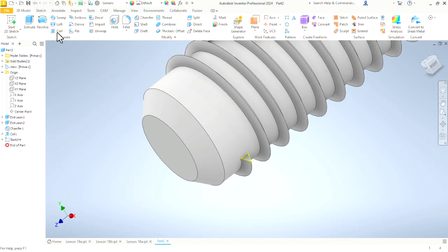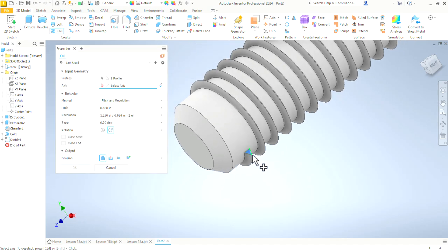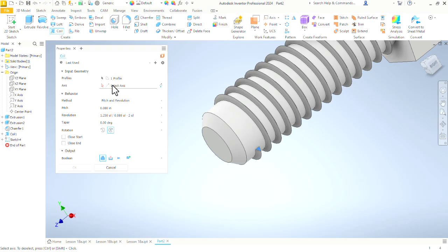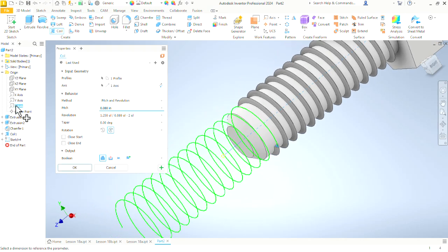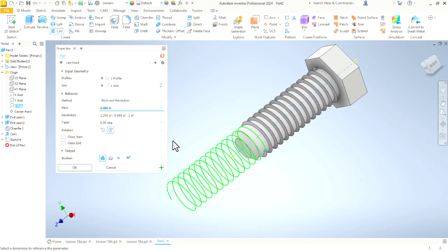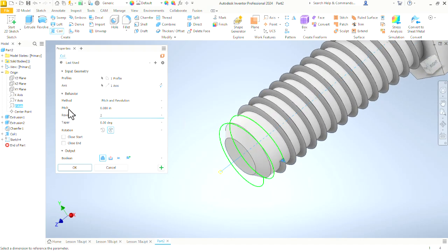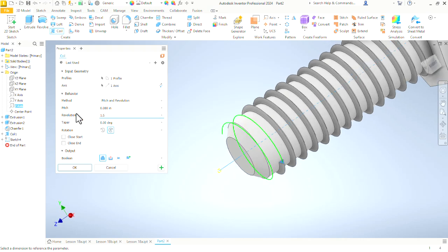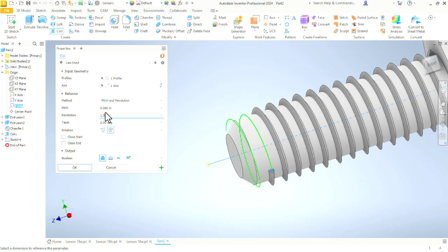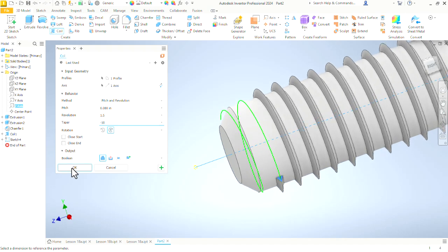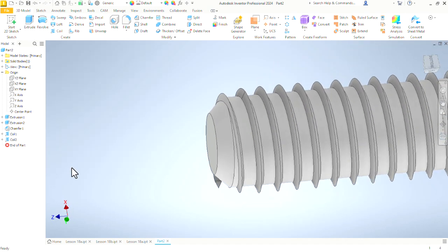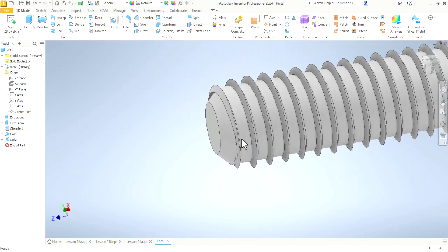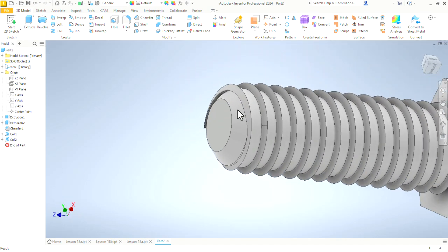Finish that 2D sketch. Go back up here again to coil. Again, it is selecting that profile. We want the Z-axis again, and see it starts. It gives us the preview here with the numbers that we had in there before. Let's keep our 80 thousandths pitch. Let's try 2 revolutions. Let's make it 1.5. That'll get us just to the end. But this time, let's taper. Let's see what a -10 degrees looks like. See, it starts to disappear, but we're coming out the end of the part.